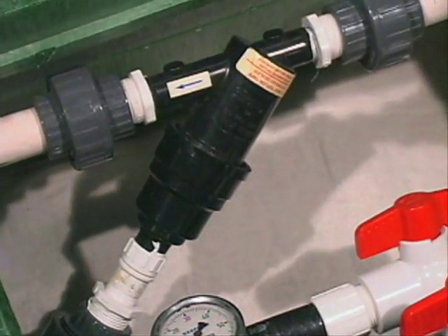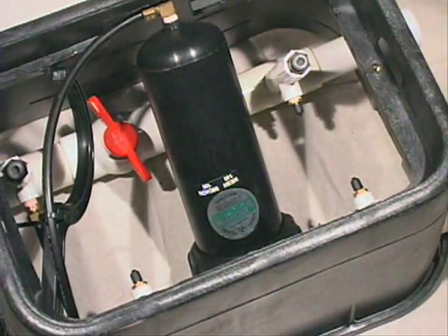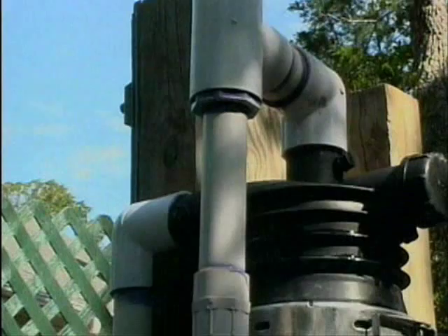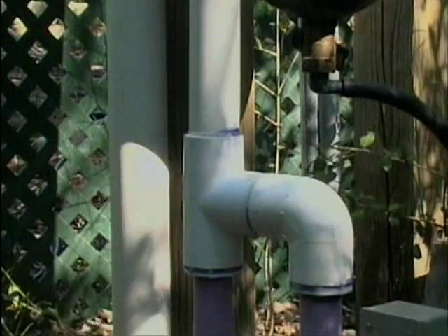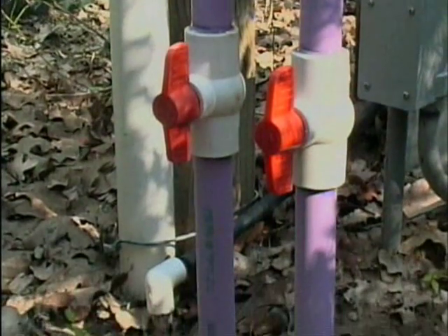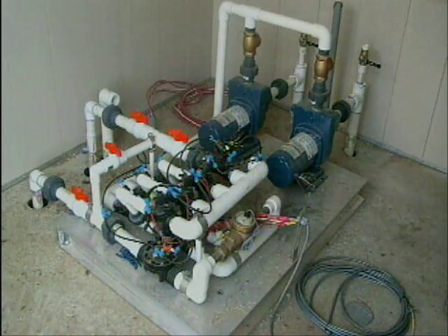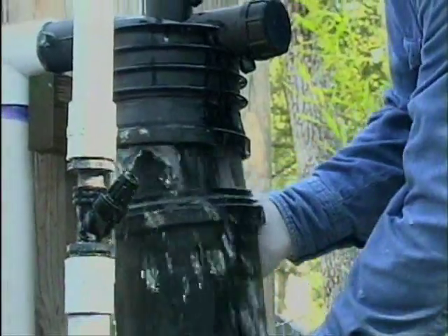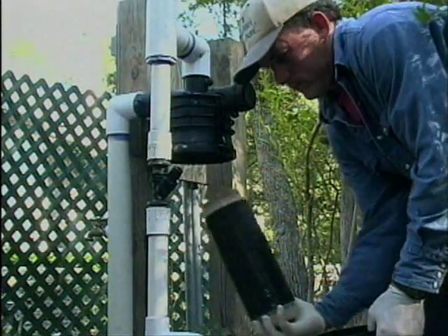Filtration can be accomplished with products ranging from a simple, manually cleaned filter to an elaborate, multi-filter, automatic backwashing system. The complexity of the filtration system depends on the quality of the effluent entering the drip tubing and the reliability of the pre-treatment system. For example, the filtration system following septic tank pre-treatment will need to remove a large quantity of solids and be a more elaborate, self-cleaning system. Filtration following sand filter pre-treatment will have minimal solids to remove and can be a manual cleaning system.